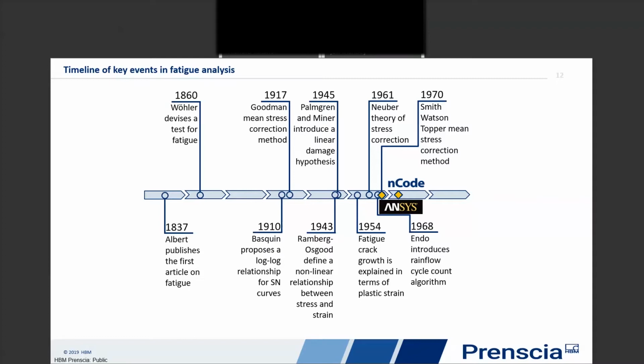So in the 1800s, there were techniques to improve the fatigue performance. The militaries in Europe were using autofrettage to leave residual stresses in gun barrels in the 1800s. Wohler designed tests and a fatigue design curve to design railroad axles. But it wasn't until the 1900s that they even knew what was causing the physics of fatigue. So all this was possible just looking empirically at what behavior was, not knowing what was physically causing it.